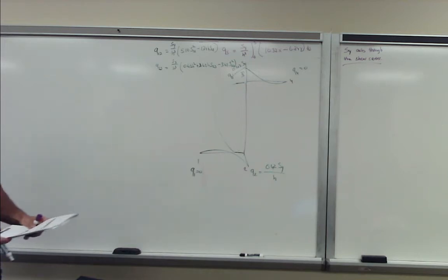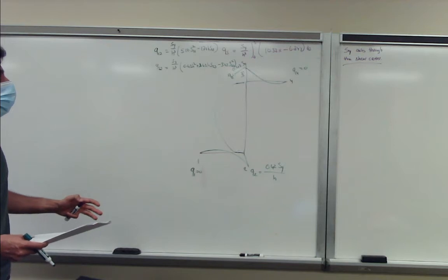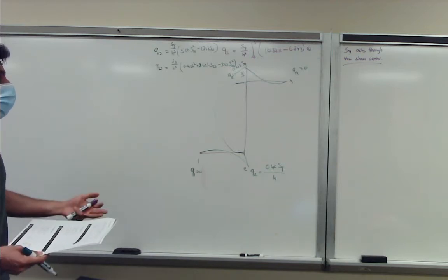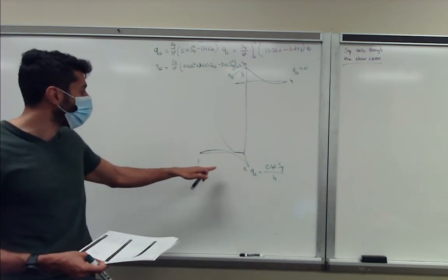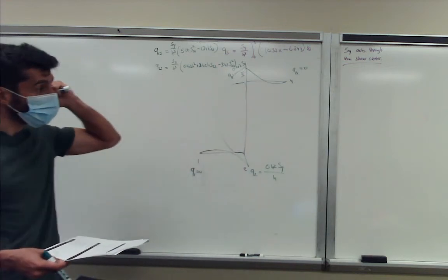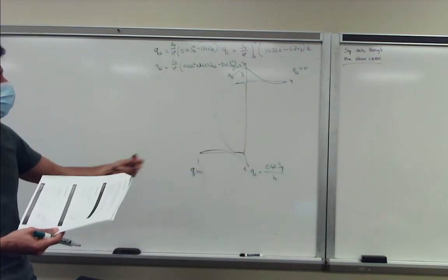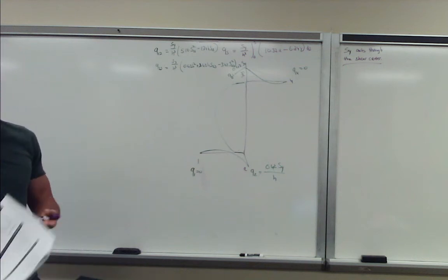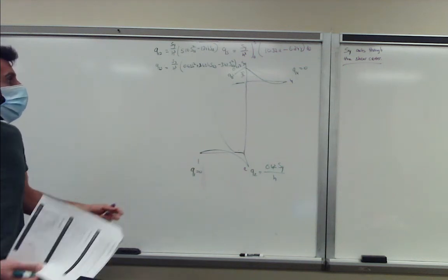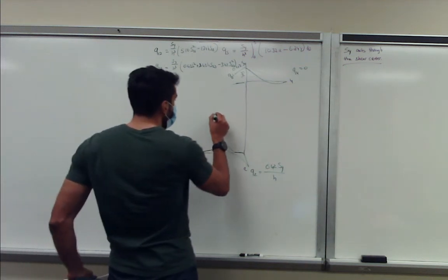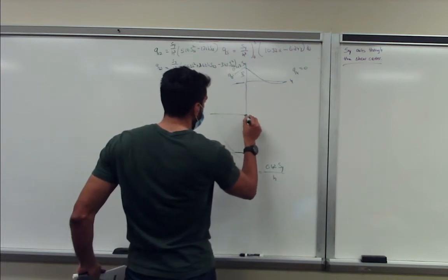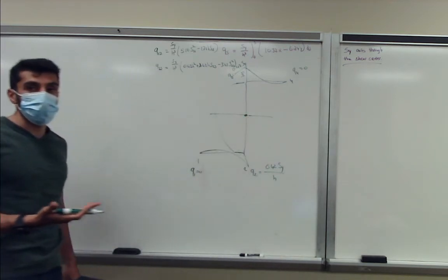Another important point is that from the shear flow, you also know what the limits are, for example at Q1, Q2, Q3, Q4. If you have the thickness of the structure equal to t, you can get the shear stress out of it. More importantly, you can also define the maximum, and by definition that would always be through the centroidal axis.